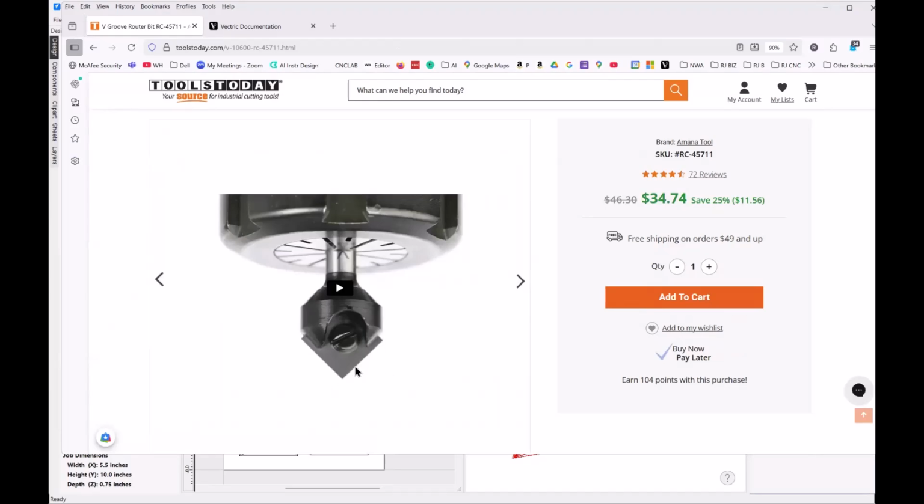and it can be rotated when one point gets dull. It cuts only on one edge. The other edge is a trailing edge. It doesn't cut on the backside, it just cuts on the one edge. So it's a single flute, which gives you a really good chip load. It's a very sharp edge because it's a very high quality carbide.